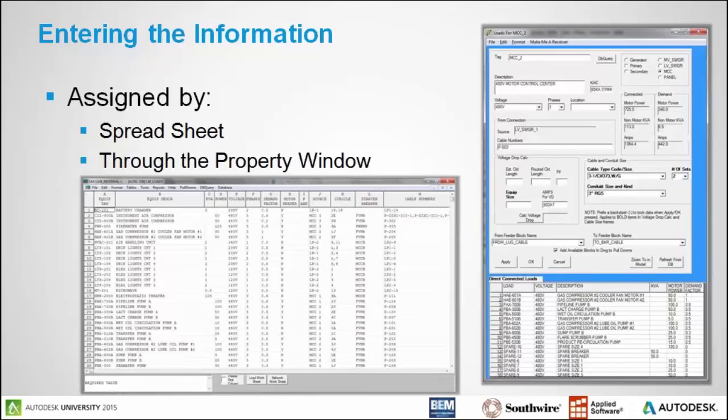So the same information that you're using now, that you're inputting now, such as the voltage, the load, whether it's in kVA for a static load or horsepower or kW for a motor load, the demand factor, number of phases, etc. This information will go into this window, and we will also assign an AutoCAD attributed block to each load so that the information can be used to build our one-line diagrams and control schematics. There's also a form that we can get information on each component in our bus network.